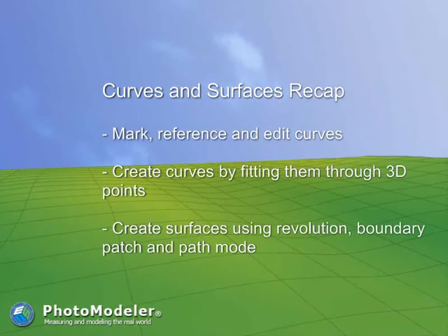This concludes the Curves and Surfaces tutorial. In this tutorial we have learned how to mark, reference, and edit curves, how to create curves by fitting through 3D points, how to create surfaces by revolution, boundary patch, and path mode.